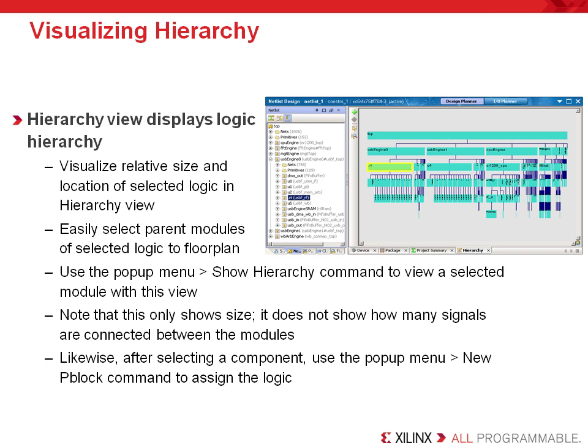Use the pop-up menu Show Hierarchy command to view a selected module with this view. This will show only the size and does not show the signals that are connected between the modules. Likewise, after selecting a component, use the pop-up menu New Pblock command to assign the logic.